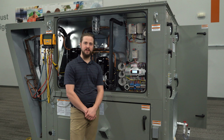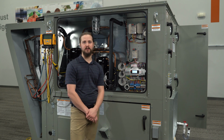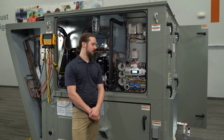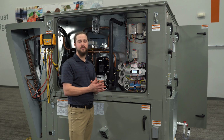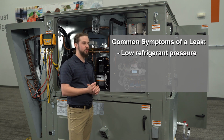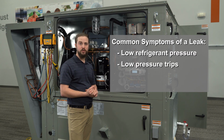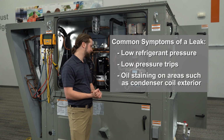Hey, I'm John Buzikowski. Today we're going to be looking at symptoms and repair of refrigerant leaks. We're going to start with some of the symptoms of a leak and how you find them. Those symptoms could include low refrigerant pressure, low pressure trips, or oil staining on the exterior of your condenser coil.